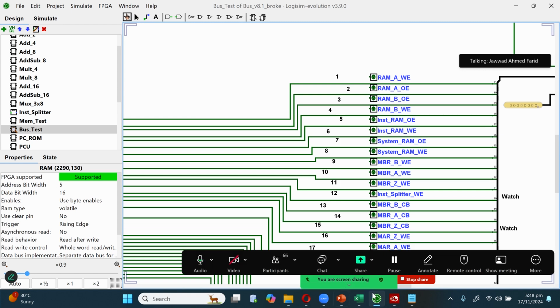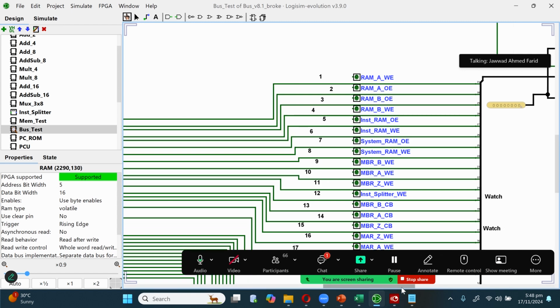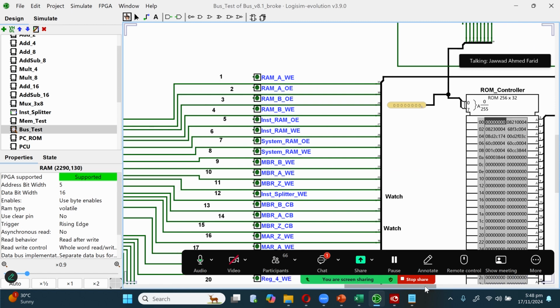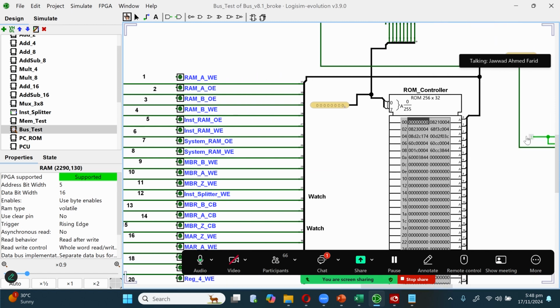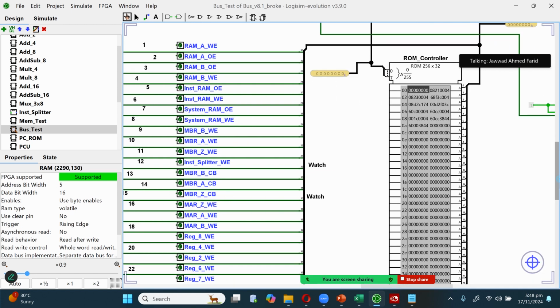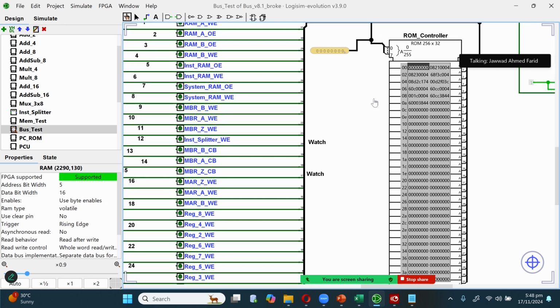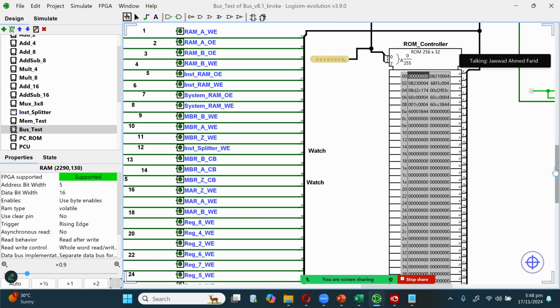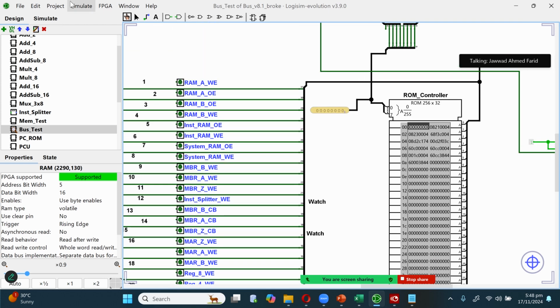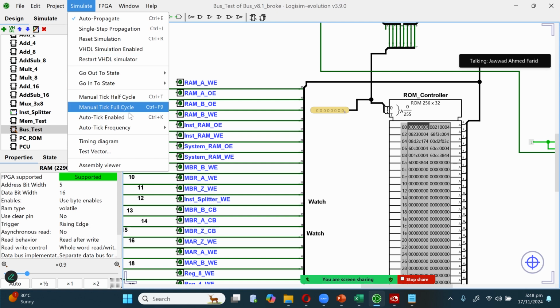ऊपर तो आपने देख लिया, you've seen how things are moving on the top side. How are things changing as far as the ROM is concerned, and how is it feeding the signals that are going out? So what all it's doing, it's given the address. So this is the address that you give it. Given the address, it picks up the relevant value and it feeds the line, the signal the lines need, and then it moves on.